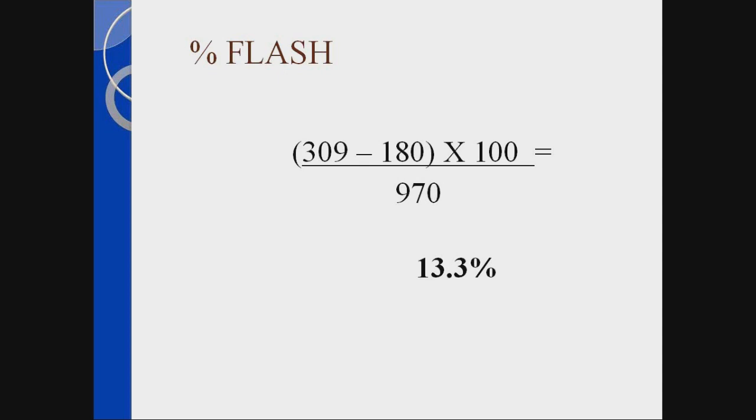The other thing you have to remember, if condensate's passing into an atmospheric system, the flash steam is going to expand somewhere around 1,600 times. Therefore, we have to make sure that we compensate the system, in the return system, for the amount of flash that's going to occur in a return system.